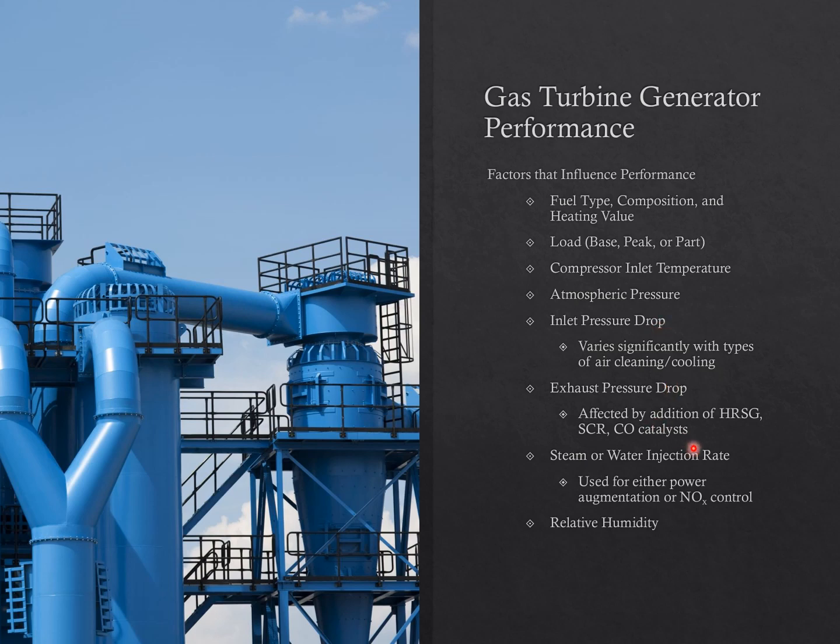And exhaust pressure, another pressure around the exhaust, usually affected by additional equipment like the HRSG unit or SCR or CO catalysis. Don't worry about the SCR and CO catalysis. If you're okay with the HRSG, the recovery system, you're okay with that. And then your steam, this one just read through. Your steam or water injection rate. This is just to balance your temperature.